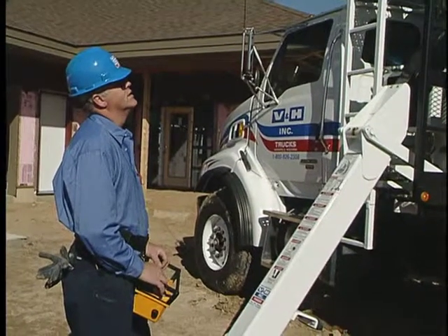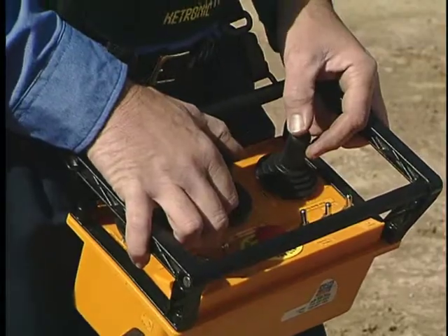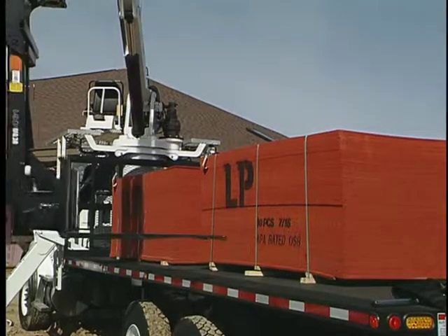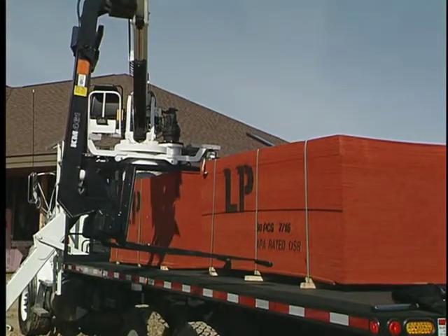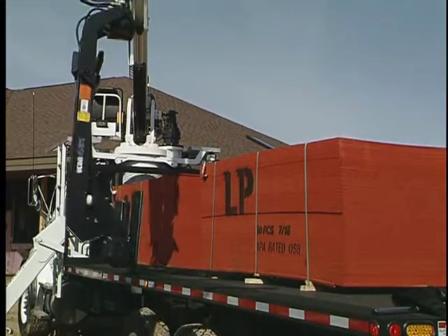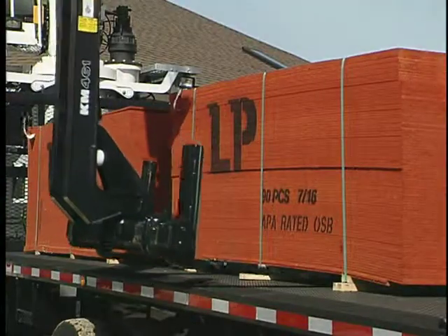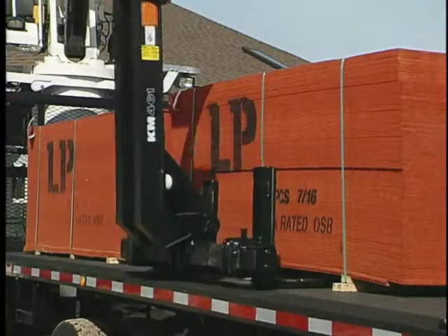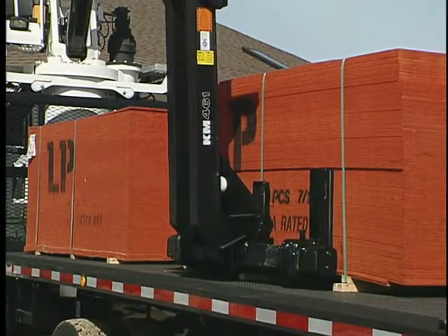Using the remote, it is somewhat easier to determine the position of the fork. The operator lets the fork naturally find its positioning by letting the nylon rollers run down the side of the load until the tines slip into place. When the fork is set, swing into the load. Lift the load very gently.